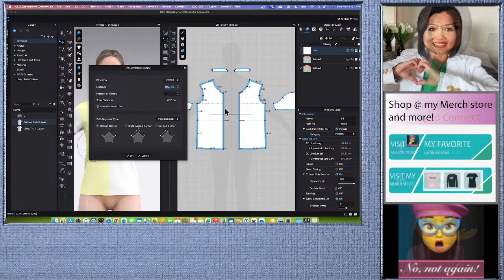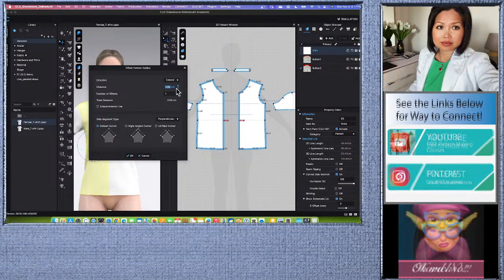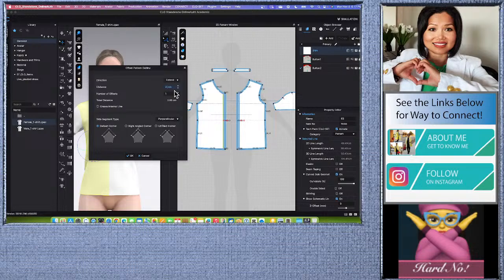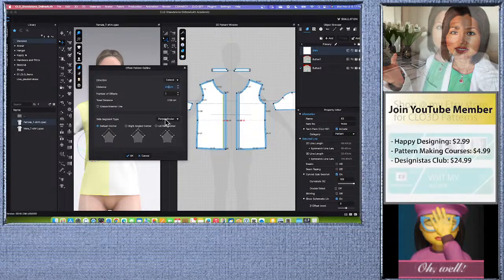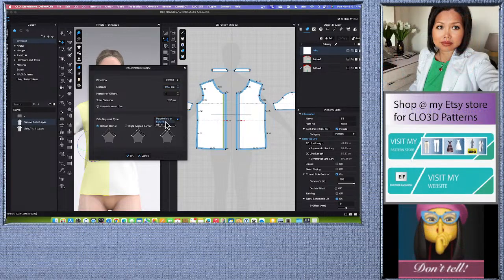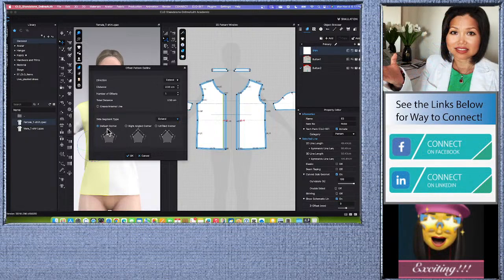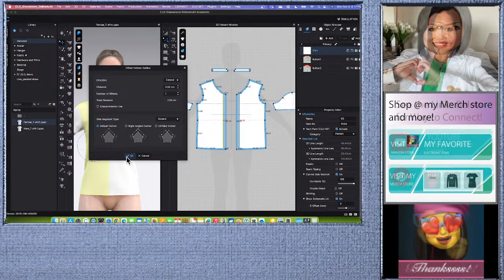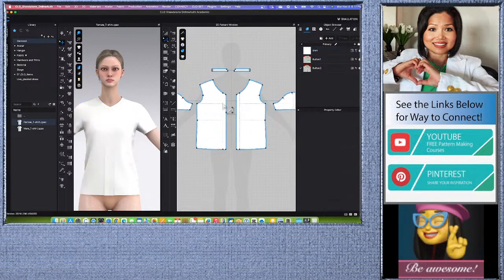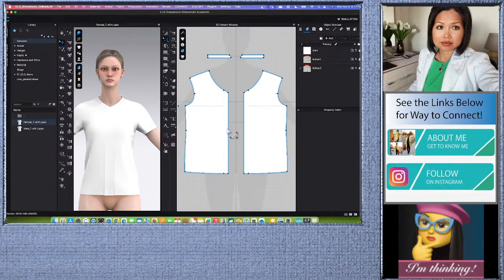Extend this between 2 to 2.5 centimeter, how you want. I recommend 2.5, a little bit big, but hey, 2.5 right there, extend. And you want to come down here, turn this to extend. Okay, and over here default corner, that is perfect, and be sure this offset number of 1 for now is excellent, and then click on OK. And since this pattern is linked, we only need to do one side.